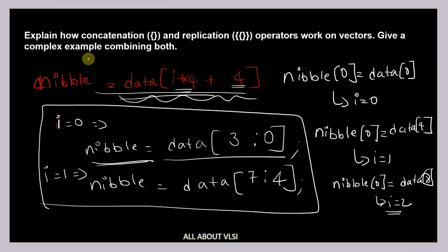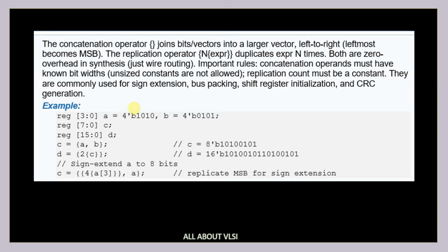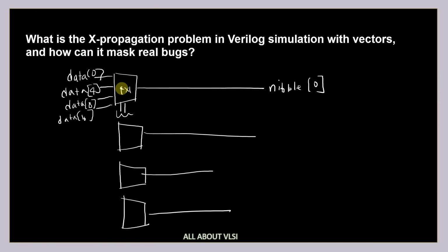Sorry, I need to go up to 32-bit, right? So not 2-bit, it will be 3-bit. So here, not a 4 cross 1 multiplexer, I'm going to have an 8 cross 1 multiplexer and the I value will be 3-bit. So I'm going to have another data of 24 and so on. I mean 20 and so on.